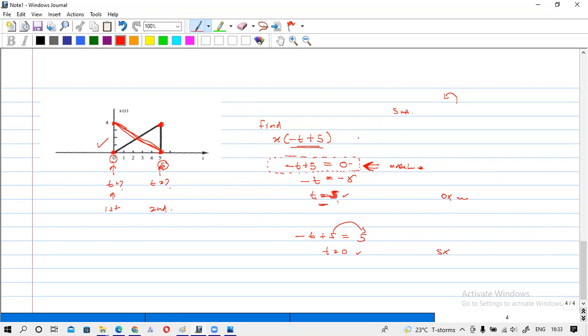So please consider this one again. Okay, I will tell. If you see this transformation, it is first time reflecting and then time shifting. So if I draw it, this is our original signal. And if I consider this time reflection part, I will get this kind of signal. What should I do to get the time reflection signal? I just consider this y-axis as the mirror and get the mirror image.